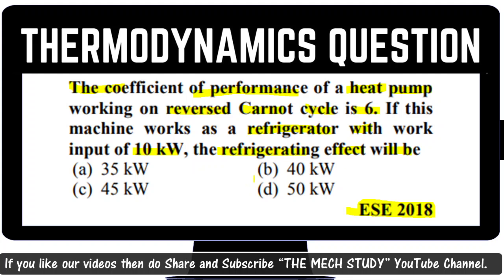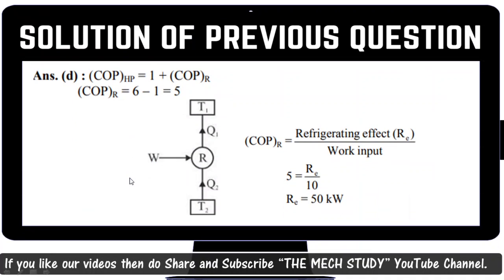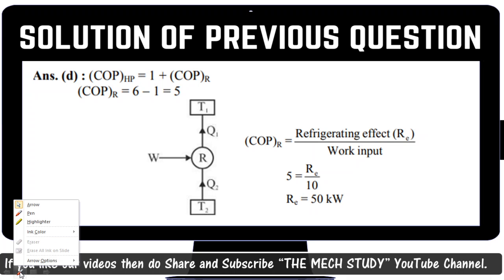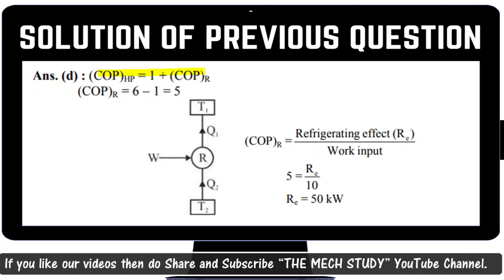I am sure, because most students always have confusion with this formula, that's why they put the wrong answer. And the wrong answer is also available in the options, so make sure that you remember these types of questions. In this question, the standard formula is: COP of heat pump equals 1 plus COP of refrigerator. Remember that, COP of HP equals 1 plus COP of R.